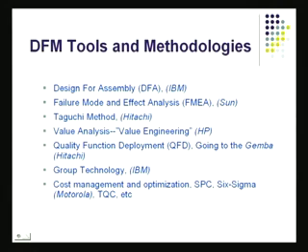This is failure mode and effect analysis. A design or a process or a product can fail many different ways. And before you go into commercial production or before you commission the final product, you've got to make sure you've done FMEA. You've tried to predict in what different ways, in what different modes can a product fail. You also have to make sure when you're doing this, you look at the effect, and you look at a couple of things. One, the first thing you look at is how likely is it going to fail? What is the likelihood of a particular mode of failure? In what different ways can it fail? That is mode.